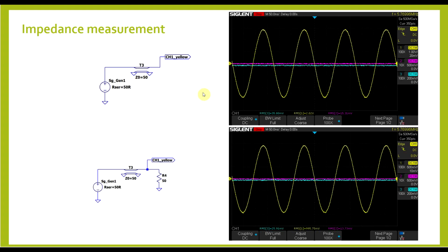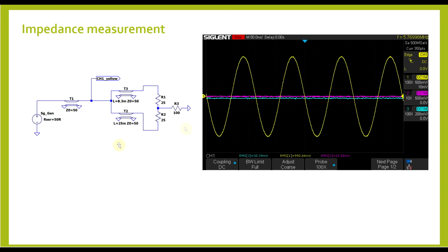If we continue with the impedance measurement, I redid the reference measurements at the new test frequency. So again we get about 2.02 volts into an open load and 0.995 into the 50 ohm termination. And if we measure the complete balun structure with the 50 ohm load, we get a very close 0.99 volts RMS. So from the input side at least, the structure is behaving as expected. It's showing 50 ohms. So it's not clear that there's anything wrong on the load side.